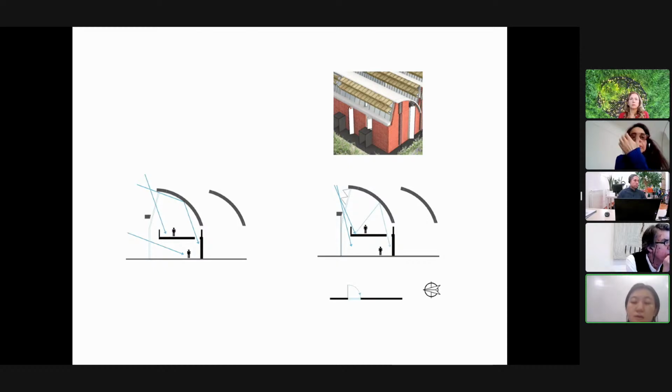Within this zone, the design of mixed use was based on the position and the relations, and also learned from the precedents. So this is one mixed module, and when it is all open to daylight, there are 2 sources, from the facade and the roof. Then it allows both levels to get daylight right from the outside. When the solar protection is closed, daylight becomes a part of the skylight. It can also reach both floors, and it could be reflected by the roof to the deeper area of the lower floor, so that the rooms are all well lit with both light and solar radiation.